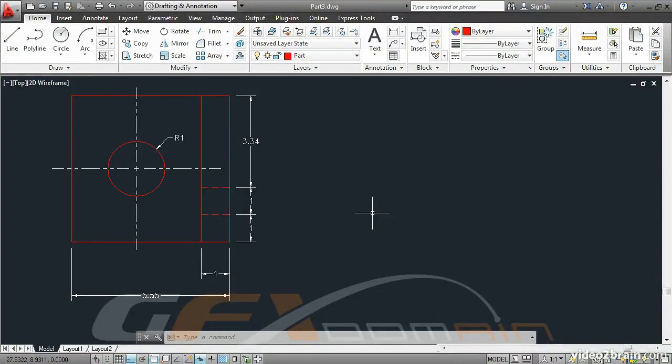In this lesson, you will learn how to use object snap tracking and will gain more drawing experience with a mechanical part project. Object snap tracking allows you to infer snap points which aren't on other existing objects. You can use object snap tracking to zero in on the significant points implied by the geometry in your drawing.